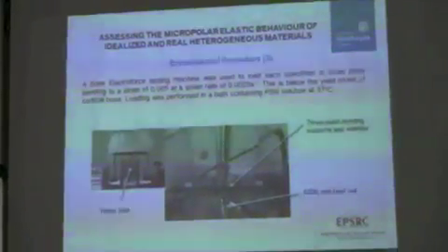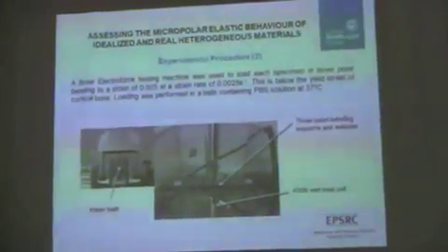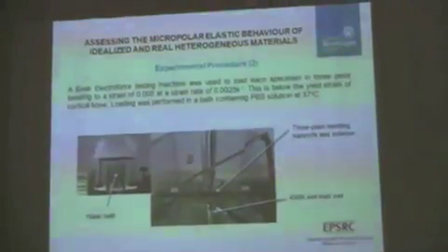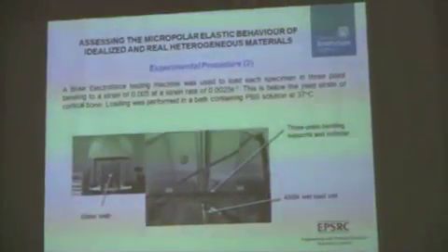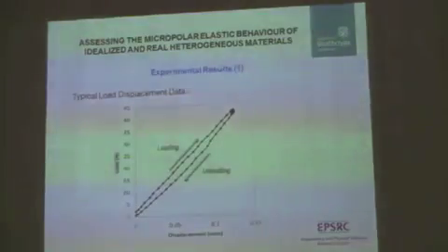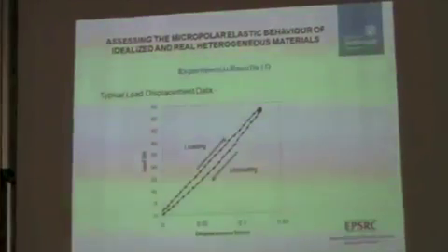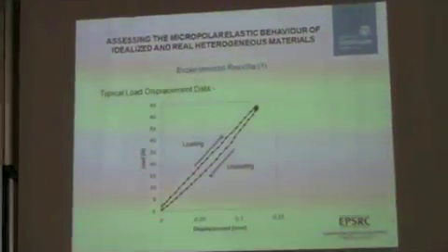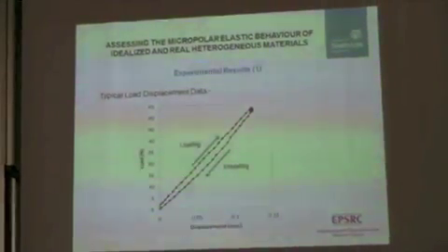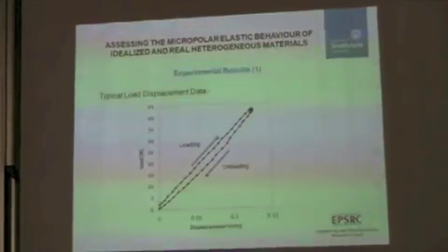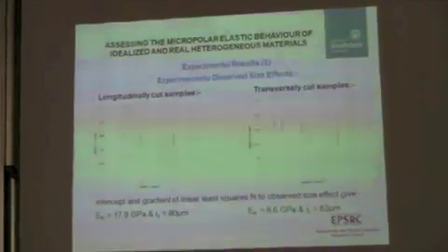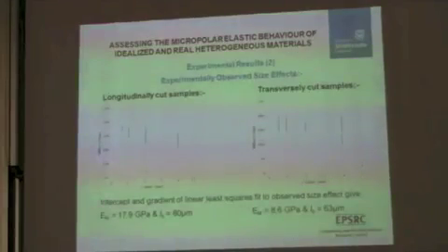The main feature is that we have a water bath in this setup so that we can test under in vivo conditions. Typically the experimental data has some hysteresis in it. We're loading, you notice, to very low loads, but we can identify the stiffness from the slope of the loading line there.